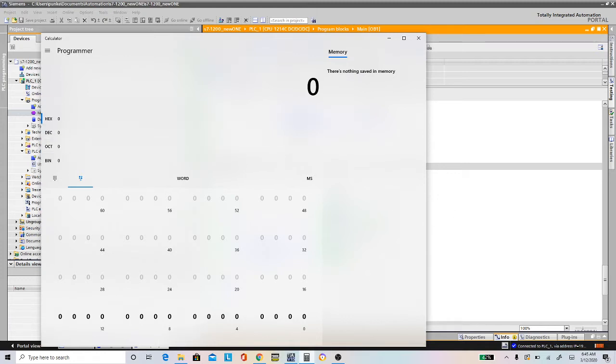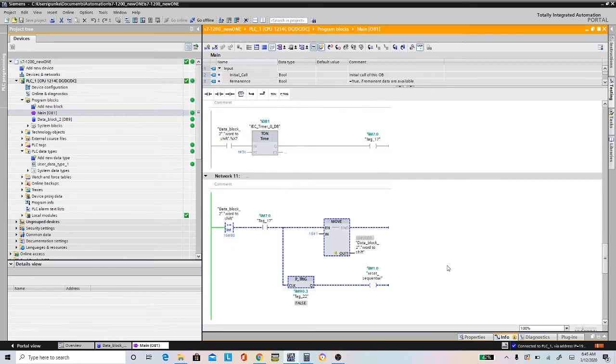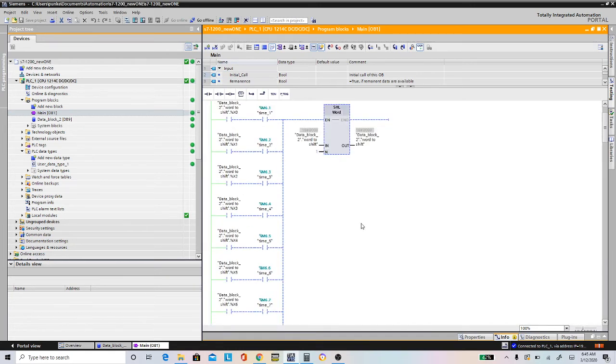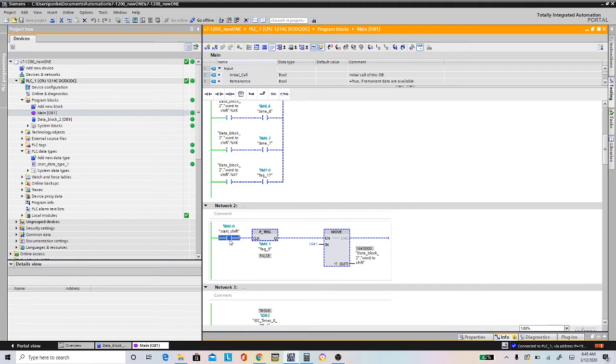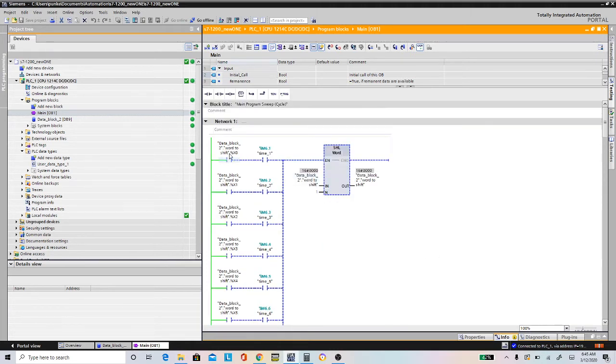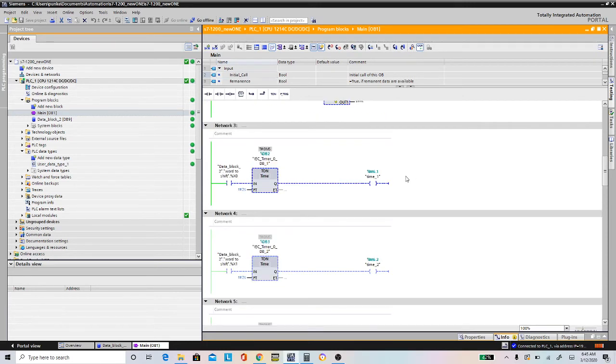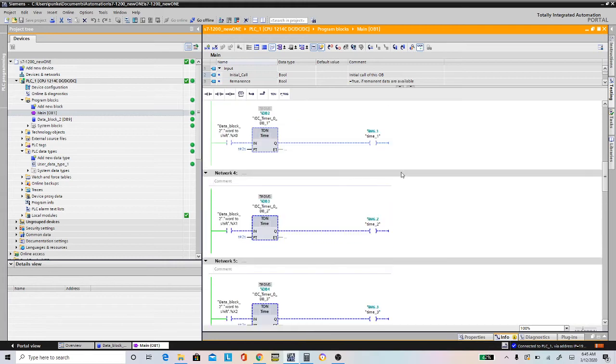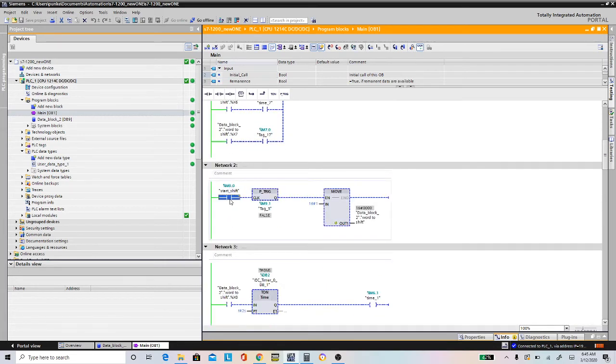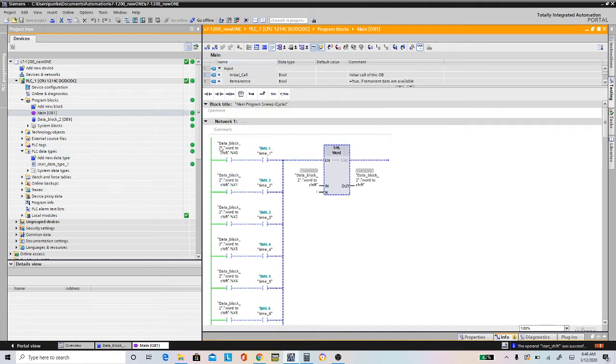That's how you start the shifting. So if you can see it from here, I am moving. When I activate this bit, it's going to have a positive trigger, and I'm going to move 16 hexadecimal 1 into the data block word to shift. So when I enter 1 in here, this bit comes on and the timer will start. Alright, let's give it a shot. Turn this on. Turn that on. You see how it comes on?